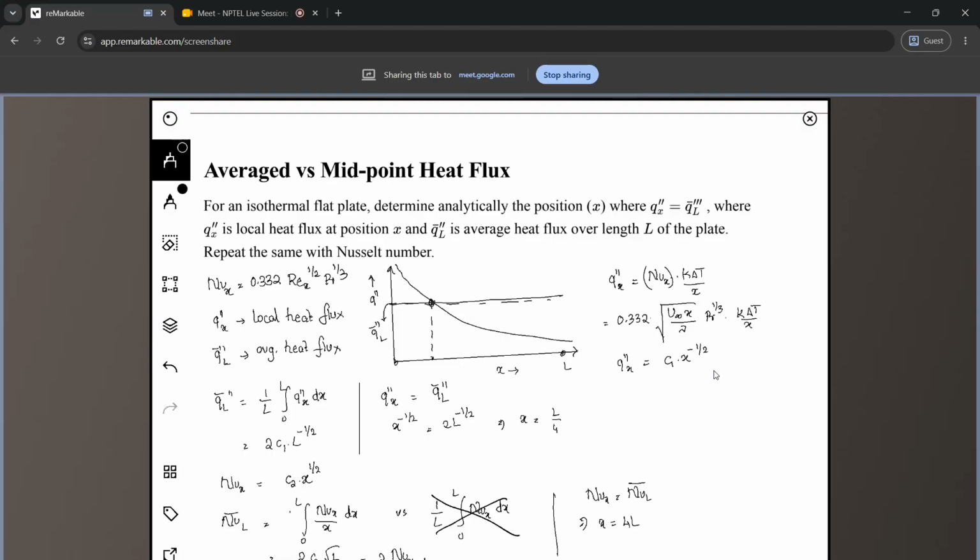Then most of the literature uses this particular definition. So once you get the simulation data, when you calculate the Nusselt number, you have to make sure that whatever code you are writing to calculate the mean Nusselt number should not be using this definition. Instead, it should use the other definition. Only then will your values match with the other literature. This is to highlight that particular point.